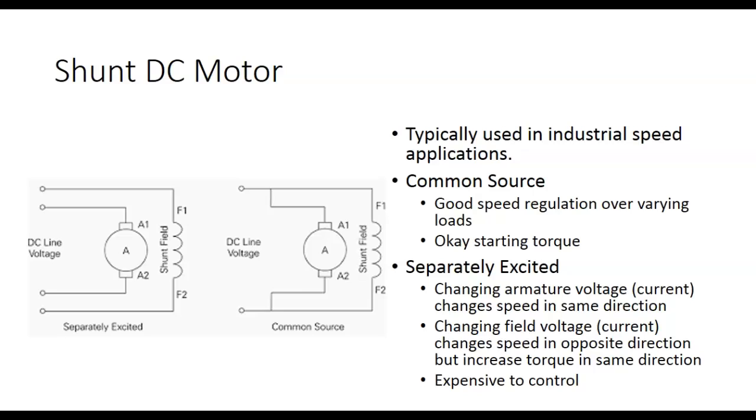This is where they were in the electronic controls, and it was using a high impedance circuit called a mag amp to run the field. And the guy got in there, and he was trying to measure the field with his voltmeter. People think that a voltmeter has infinite resistance. It doesn't. So Dennis got in there and put his meter across that high impedance sensor that sensed the field, and shut the line down.